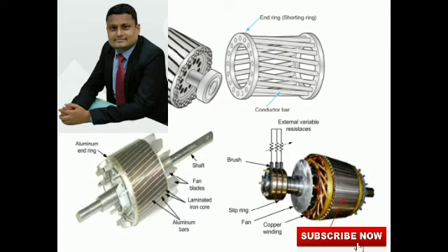Due to larger air gap, there is reduced magnetic pull, that means less effect of eccentricity. Reduced tooth pulsation, that is variation due to slotting is small, so the tooth pulsation also gets reduced, magnetic pull gets reduced, and the noise will also get reduced due to reduced zigzag reactance.